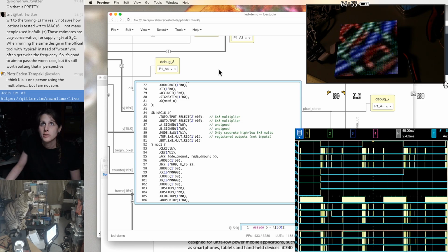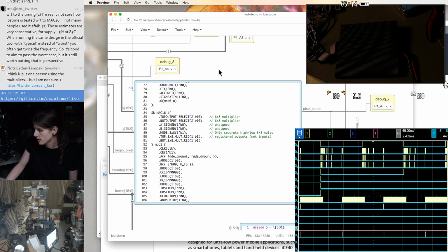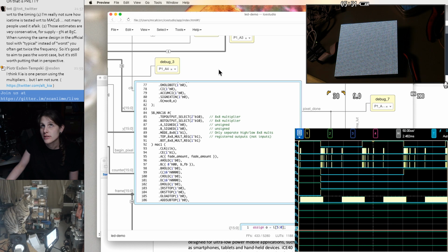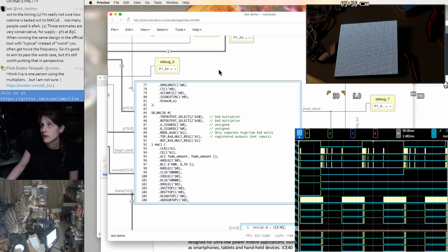Why is there just one LSB different between saturating completely and not really? I'd really like to know what this actual value is. 1, 2, 3, 4, 5, 17, 18, 19, 20, 29, 30. Okay, 32 it starts to saturate. This is 31. Still saturated. 30.